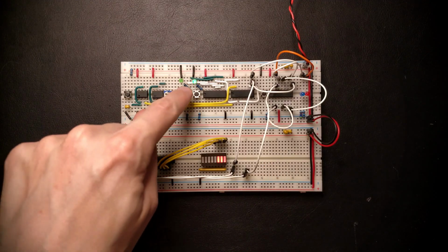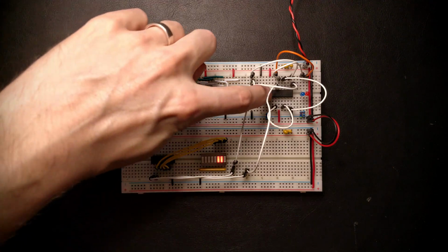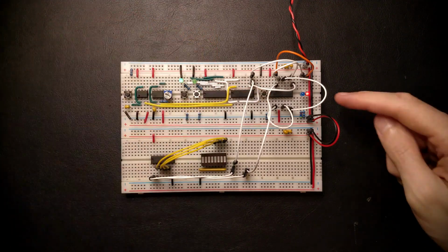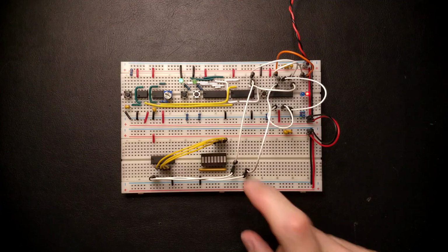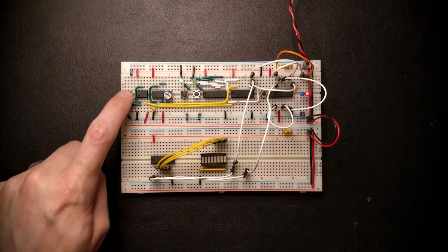First, I'll switch to single stepping mode so we can control the clock. Then hit the reset button, which causes the reset line to go high. That causes the counter to go into reset state. Now, it should take 4 clock ticks until the reset drops to 0. 1, 2, 3, 4, and the reset goes off, and the counter starts counting.